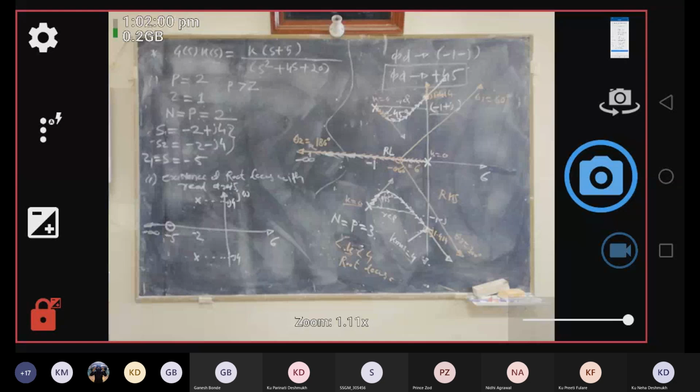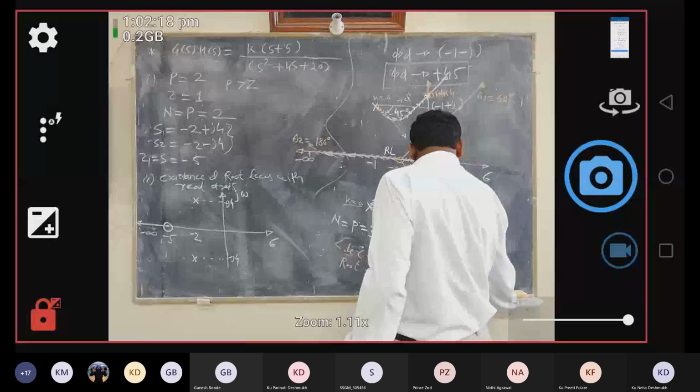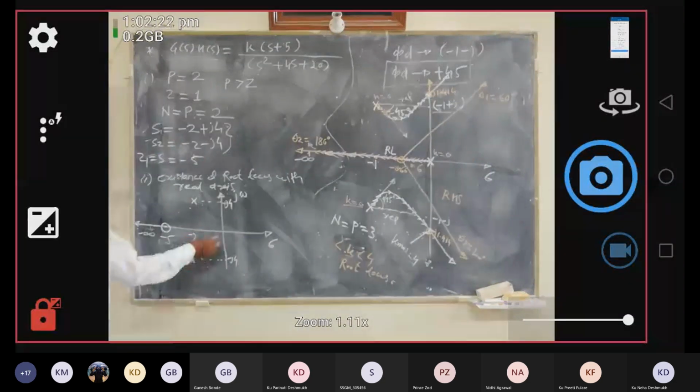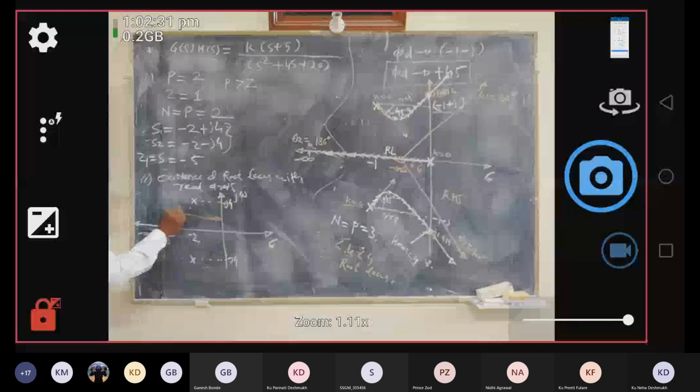Then show the path of existence of root locus and non-root locus along the real axis. Please do this. While doing this, whichever is the first pole or zero on the real axis, we divide sections from it. So this is my first section.